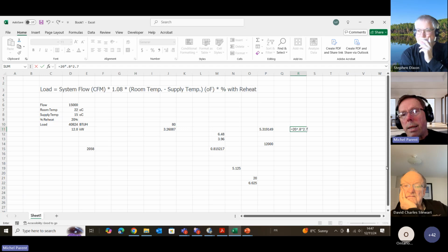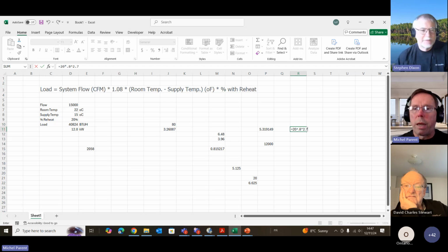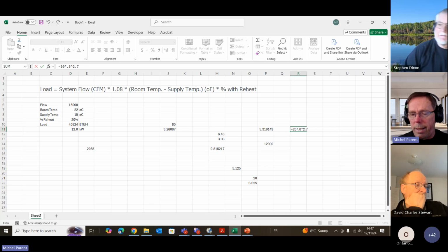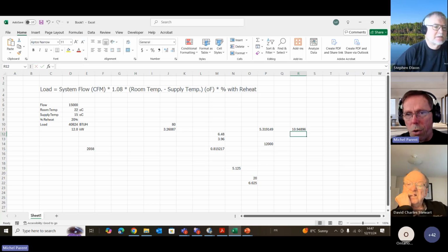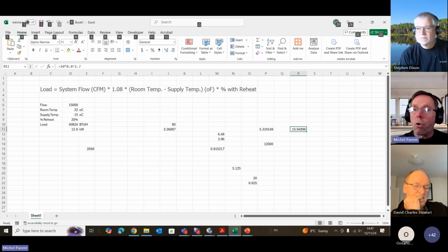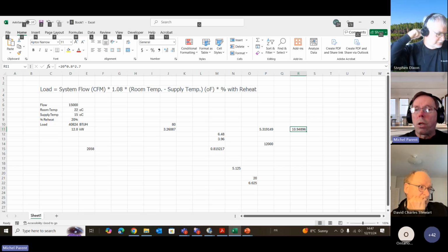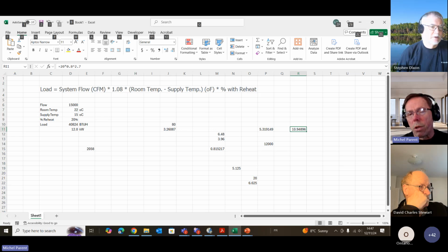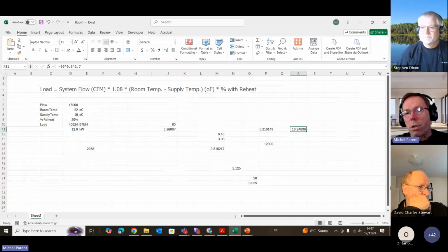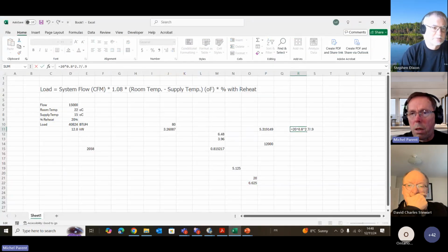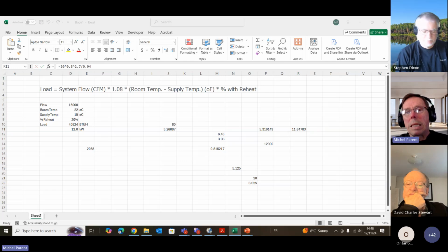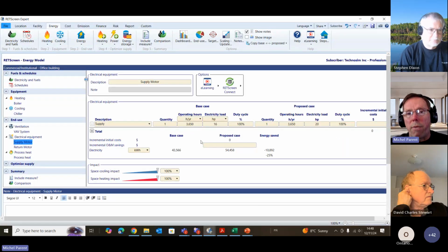Yeah, and as Stephen said, it should be cubed. But because of practical constraints, usually the theory says it's cubed, but I'm going to go with the exponent 2.7. So that motor on average will not draw 20, it'll draw 10.9. Actually, the motor itself will draw more than that. There's a motor efficiency, which I'm going to divide by 0.94. So it's 11.6. So you would have to replace that by 11.6.